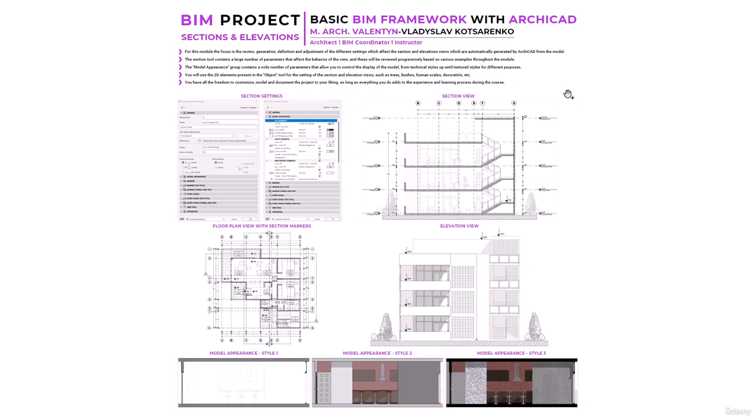And once we're done dimensioning the project, now we jump into how you can work with sections and elevations. I'm going to explain pretty much all the parameters within the section tool, how you can automate up to 80% of the workflow behind a section view. So you generate something like this, and then you just need to position the hatch representing the terrain, a little bit of the setting of the section, but pretty much the level, the automatic dimensions, the grids, the visualization is something that is automatically done by the section settings, okay?